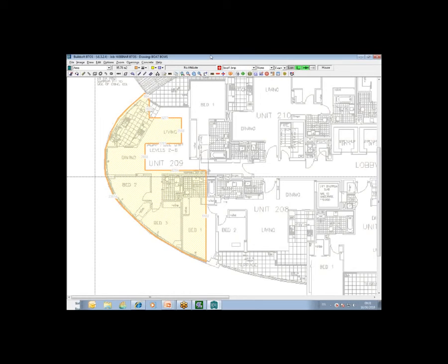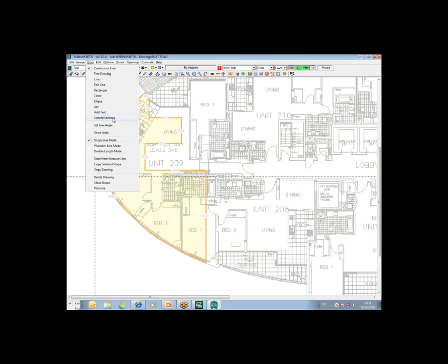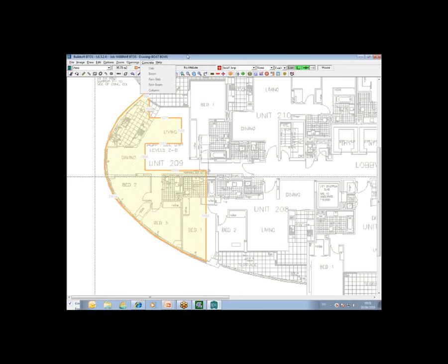You can also do that curved section in area takeoff, lineal takeoff, vertical takeoff, any takeoff that is available there. You can use the curved section in it, and it is available on the draw drop-down menu, curved section. As such, you turn it on when you come to your curved section, and you turn it off when you've completed the takeoff of that curved section.